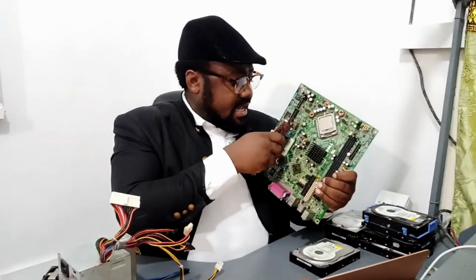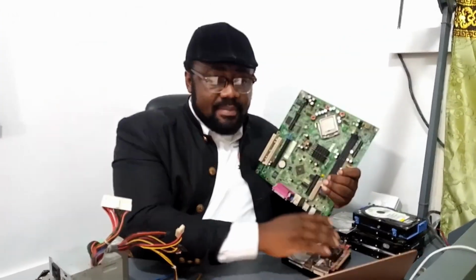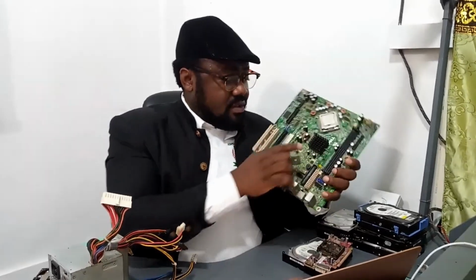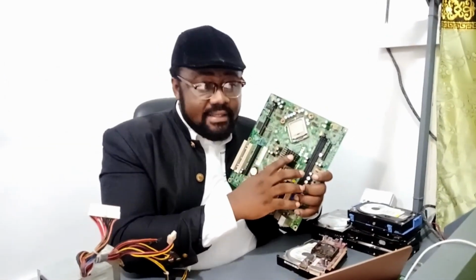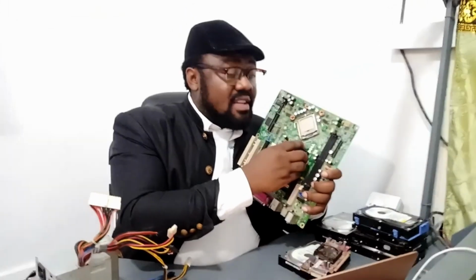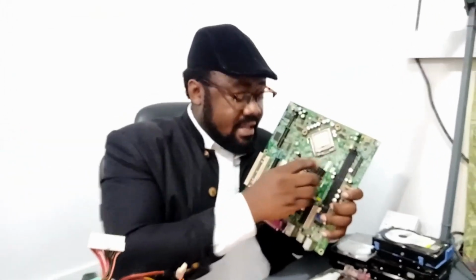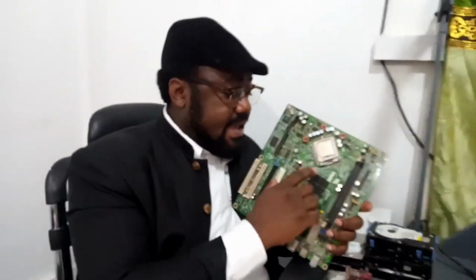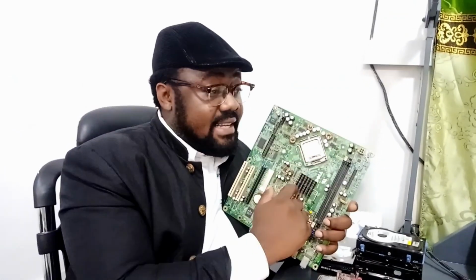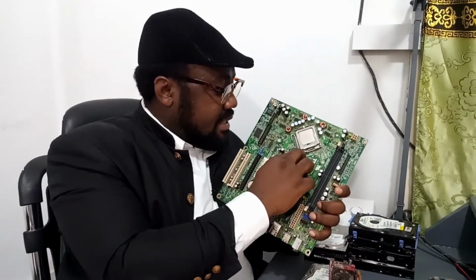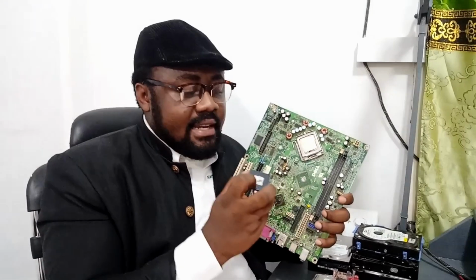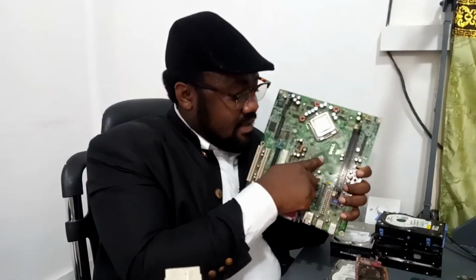So just to recap on that, because I don't want you to forget. Now, we also talked about the two bridges, and we said they are together called a chipset. The first one here is called the north bridge, and the second one here is called the what? The south bridge. And the north bridge is under this heatsink. This is a small heatsink. Let me remove this heatsink again. When I remove it, you see that there's some dried paste here. We have some on top here.